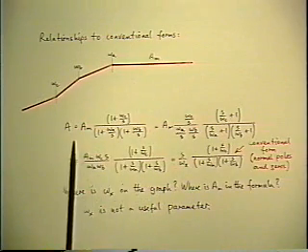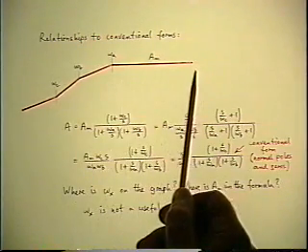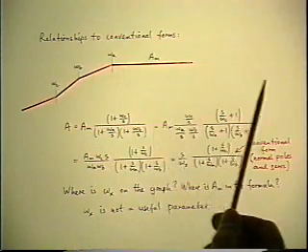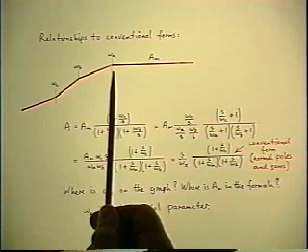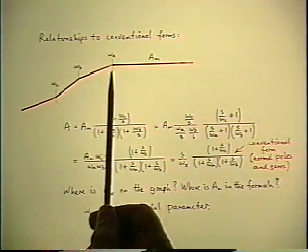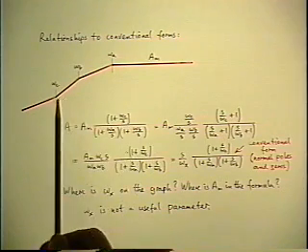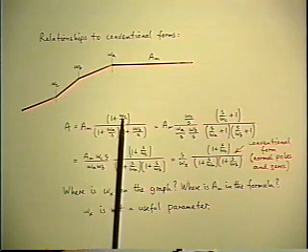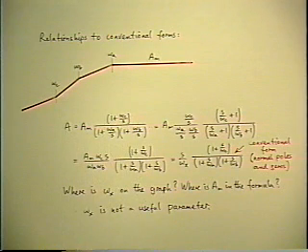the expression by writing A equals A_M. That establishes this flat gain as a reference. You look up in frequency, nothing happens. You look down in frequency, and you encounter first the inverted pole at omega A, another one at omega B, and finally the inverted zero at omega C. So this is the format that I've recommended.